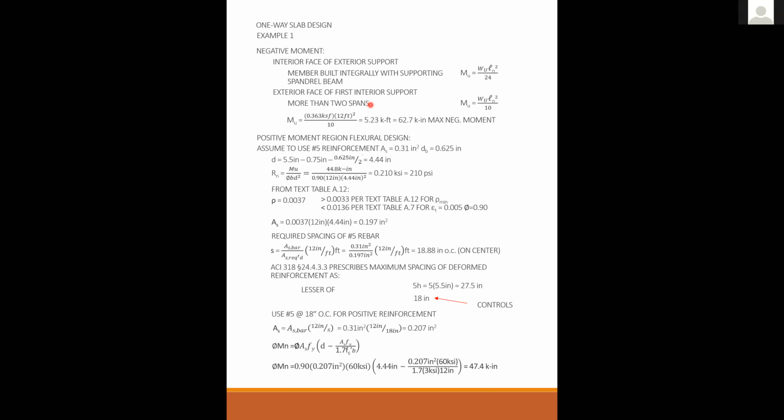I have a question on the spacing, Professor. Okay, can you go back a little bit? Sure, slide. So we're basically comparing the 18.88 to 27.5 and 18, right? Yes. And which one of the three is less? Yes. This is one of those things where the lesser spacing is more steel. The more you space it out, the less steel you're providing.